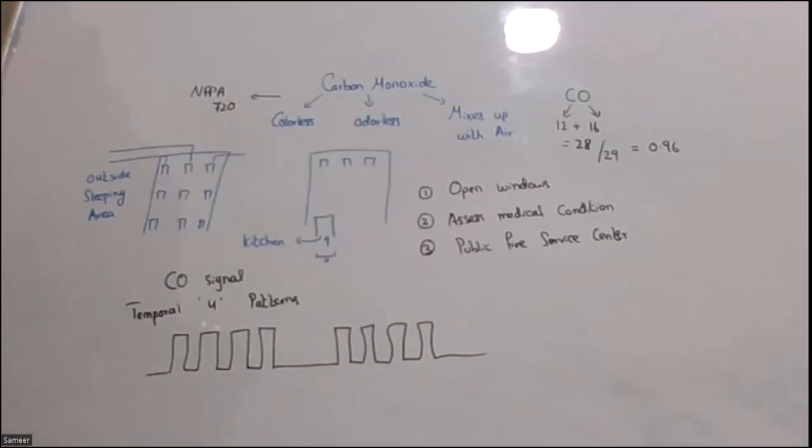The important considerations of a fire alarm system are the inspection, testing, and maintenance. First of all, in a fire alarm control panel, we usually check the batteries of the control panel, because whenever a fire occurs, the first thing is that the authority power will always be disconnected. So your whole system is going to run on the batteries.